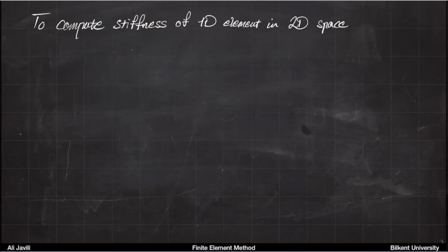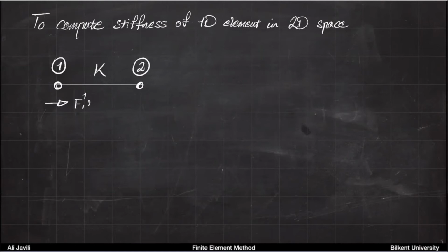If I want to draw the problem, it is really this. Let's say you have a member like this, and again, this is a 1D member, you can think of it interchangeably as a truss or as a spring. It doesn't matter. Let's say this thing has 2 nodes, and we learned that at node 1 you have F1 and U1, at node 2 you have F2 and U2.